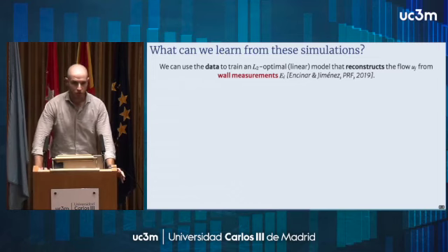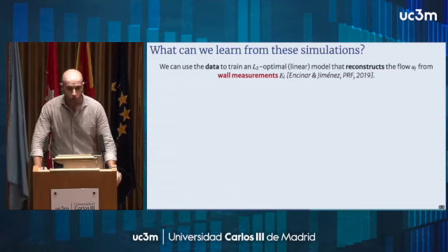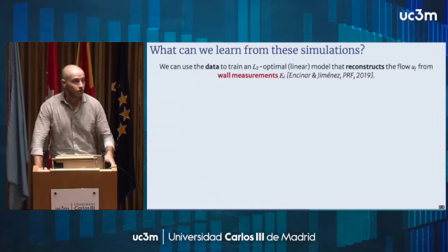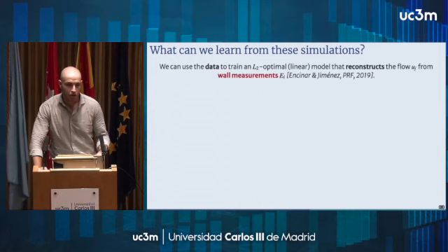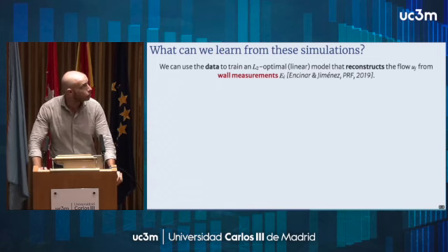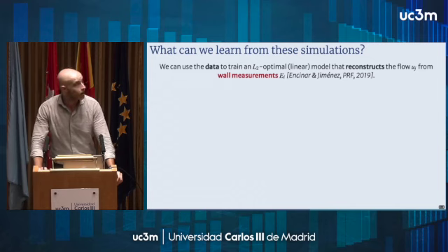With this data, you can do a lot, but the case I wanted to talk about today is that we wanted to see if we could observe the turbulent flow from the wall. So in a practical application, if you want to know the state of the turbulent flow and you don't have a PIV and you don't have a DNS, your sensors are going to be located in the wall, and you may care about the state of the flow for control, predictability, or things like that. And what we did is we decided to see how far we could push a linear model for this task.